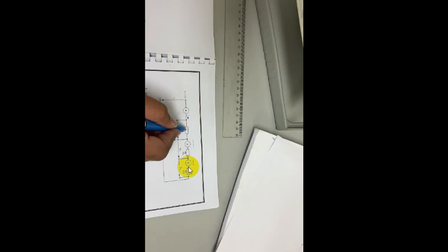There is no ammeter here. Third, we will short these two and put this ammeter and calculate the current. Our main aim is to calculate the current and the voltage across each resistor, and see whether there is any change in the voltage after each resistance.